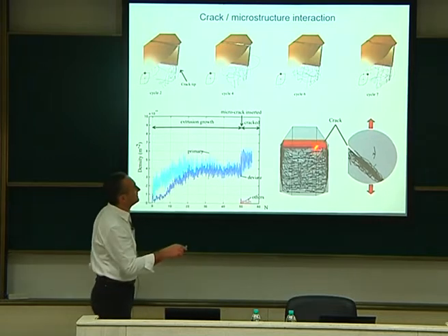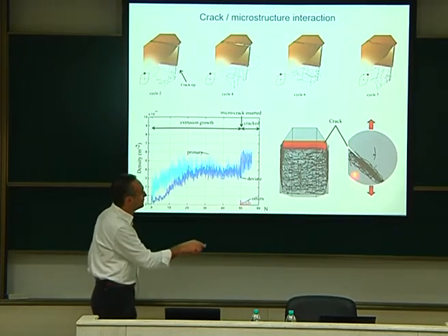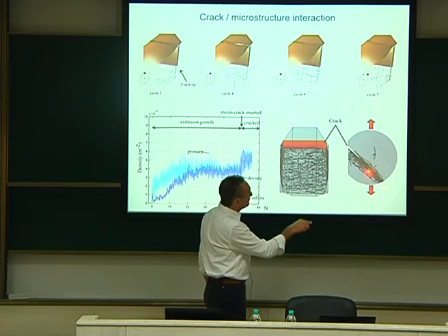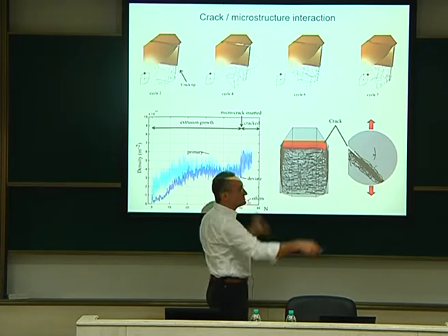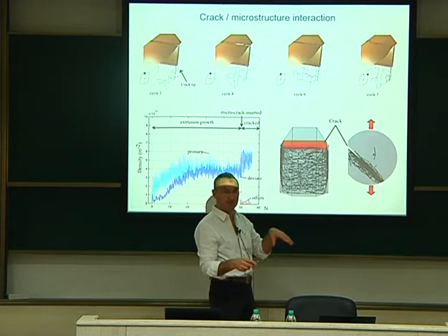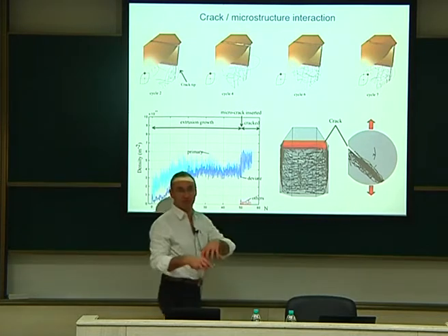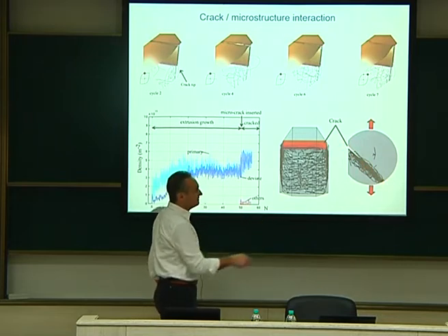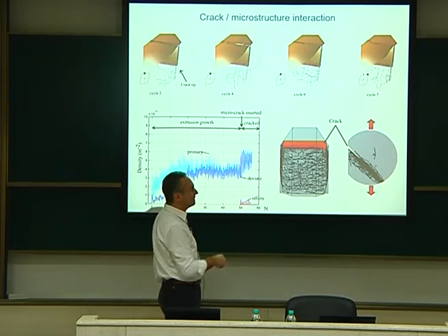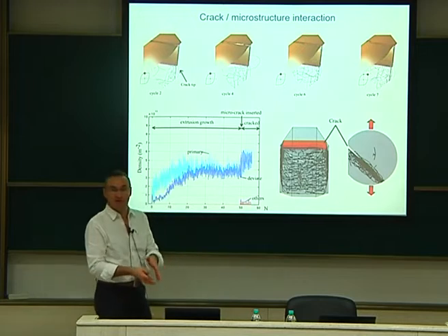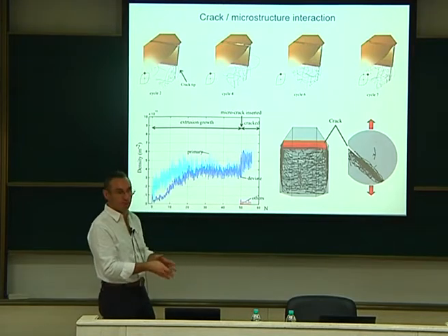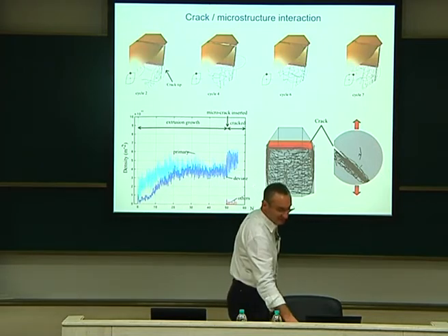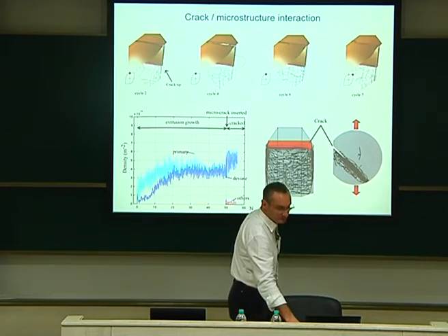And what you can see is that locally, at that stage, it looks like that. You have something which is quite compatible. You have some plasticity which is expanding ahead of the crack. You don't have some slip dispersion, although we put a lot of dislocation sources, right? It could have made a lot of noise and developed a microstructure, and it didn't. There is some nice, let's say, collaboration between the dislocations and the crack. So they are happy to be together, as if it was indeed a good way to introduce the crack. I don't say that this is the reality, but I say it's not stupid. This is something that is possible.